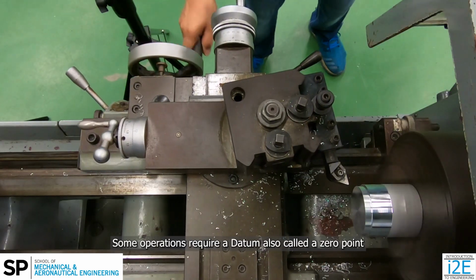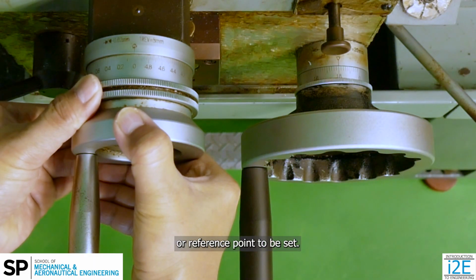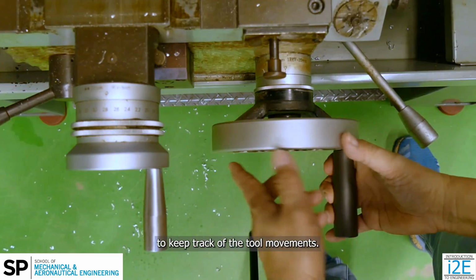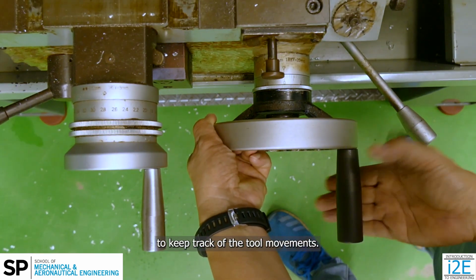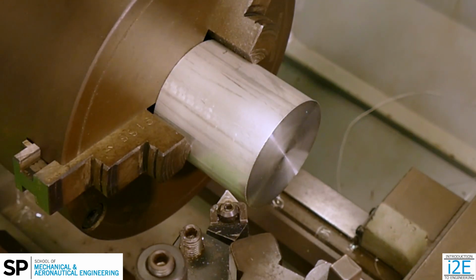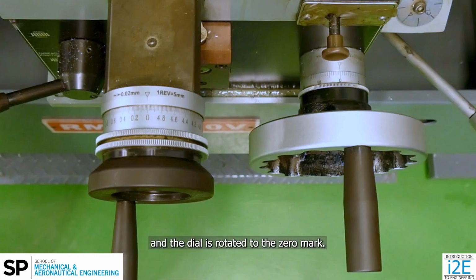Some operations require a datum, also called a 0 point or reference point, to be set. Setting a datum allows the use of the handwheel dials to keep track of the tool movements. When setting a datum, the tool is moved to the workpiece surface, and the dial is rotated to the 0 mark.